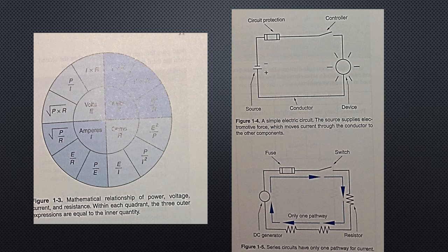There are several types of circuits. The various types are differentiated by the arrangement of the resistors and other elements. There are series circuits, parallel circuits, and complex circuits. Series circuits. A series circuit, figure 1-5, is a circuit in which the loads are connected in such a way that there is only one current path. As shown in the illustration, the current must pass through the first resistor, then the second, and then the third before returning to the source.